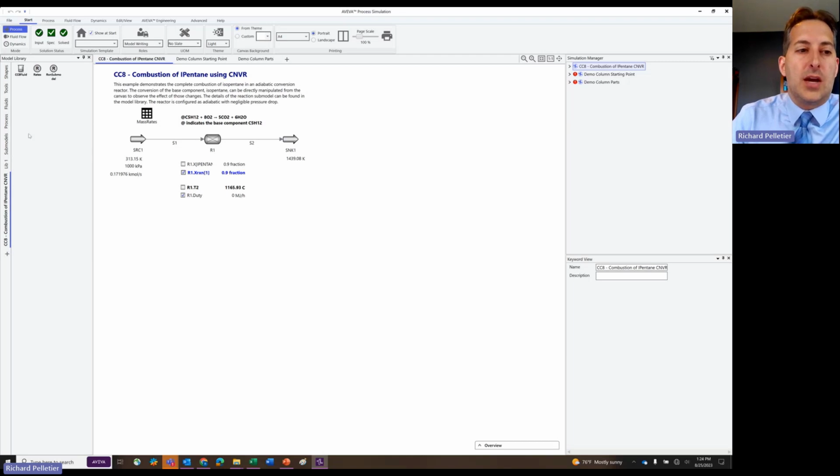And so if I don't copy this over and I simply point it to this lib1 model library, when I create my simx file and give it to someone else, or try to use it again in the future and import it, if I don't have lib1, it's not going to be able to find the reaction submodel, right? So it's always good practice to store your customizations in your simulation model library. And so I have it stored here now.